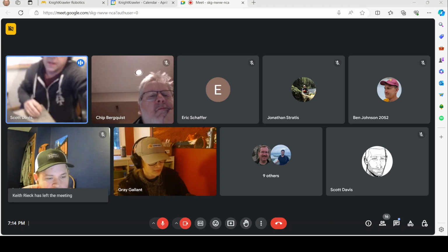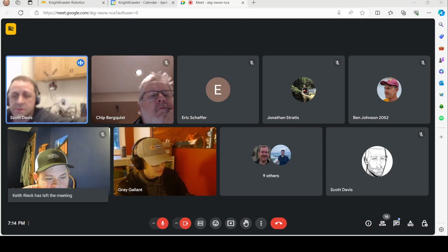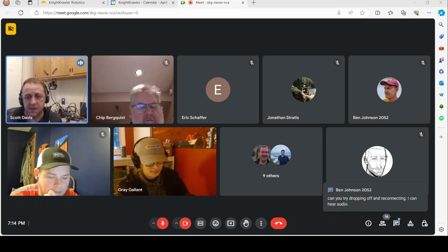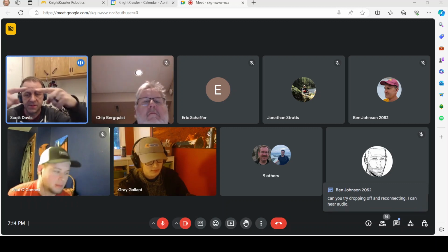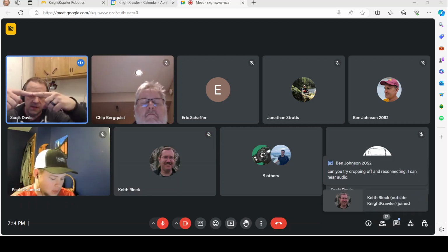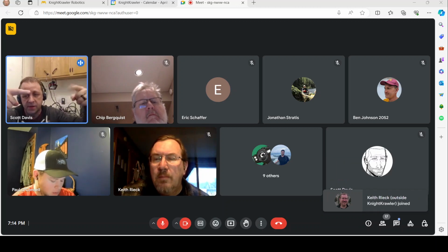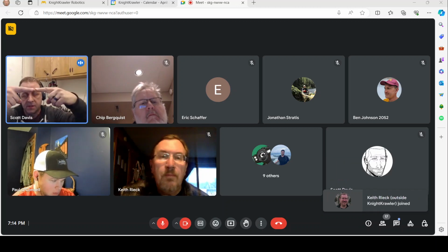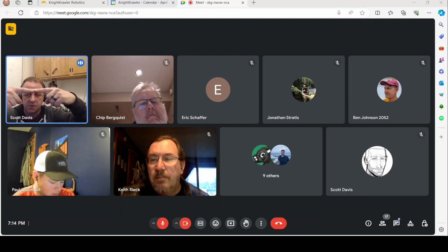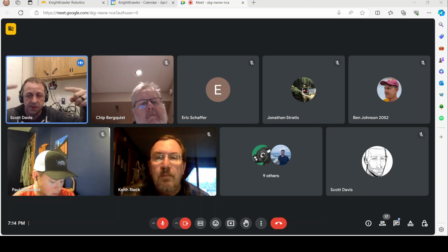So I'm going to use my hands, I think, to demonstrate this. If you're new to circuits, this is a closed circuit where you've completed the connection. So let's say you've got something over here that's reading the pin and something over here that's supplying either a ground or a power source. When the circuit's open, it's called floating.